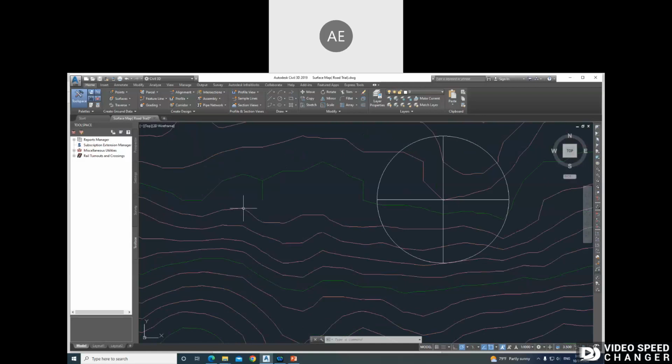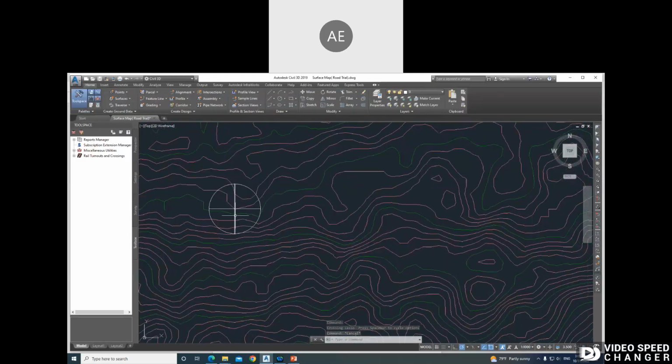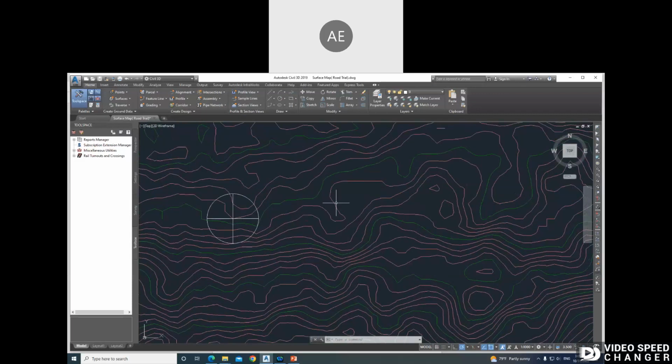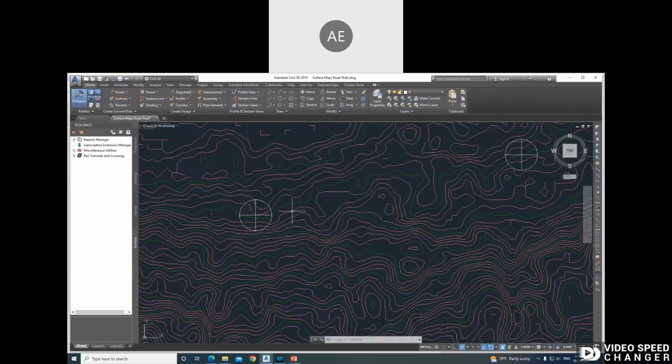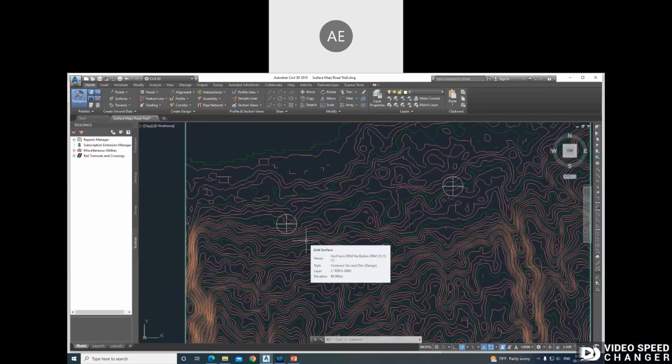So if I go in this direction, either I'm going upward or downward. What I know is that I'm changing the elevation. Why I'm saying that? Because guys, when you need to design the road, you have to choose the trajectory of the alignment along the contour lines, because otherwise you will have steep slopes. And this is a problem. If you want to understand it more later on, once I finish the problem, you can draw an alignment in this direction, and then you will export and visualize the section. You will see that we have elevations, very steep elevations.